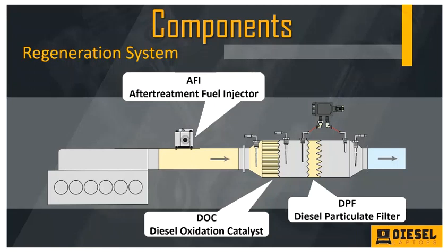And when you have that fuel hitting that DOC with the precious metal wash, you're going to get a chemical reaction, which is going to give you a lot of heat transfer. You're going to go from 500-600 degrees, and because of that fuel hitting that face of that DOC, we're going to take that 500 and 600 degrees and turn it into 1100-1200 degrees.